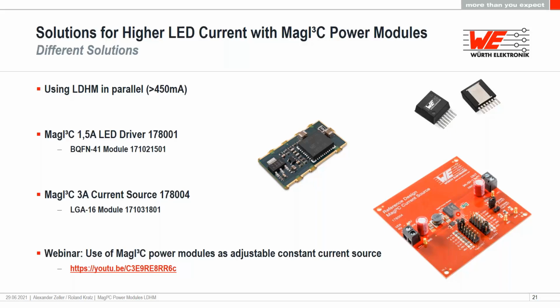We have a video about that because the compensation of this is not really difficult. Usually for the compensation, you need a proportional factor and an integrational factor, and here you only need an integration factor. This operational amplifier is just an integrator.